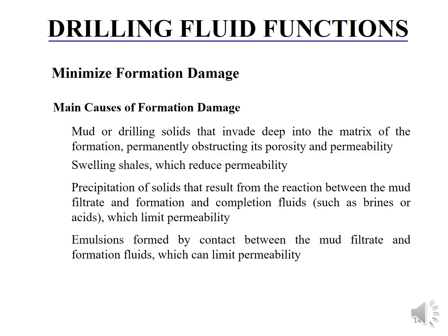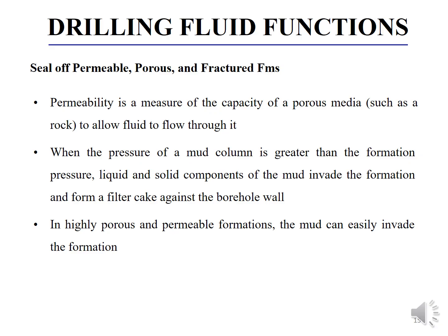So main causes of formation damage: mud or drilling solids that invade deep into the matrix of the formation, permanently obstructing its porosity and permeability; swelling shales which reduce permeability; precipitation of the solids that result from the reaction between the mud filtrate and the formation and completion fluids, which limit permeability; and also emulsions formed by contact between the mud filtrate and the formation fluids, which also tend to limit permeability. So seal off permeable, porous and fractured formations.